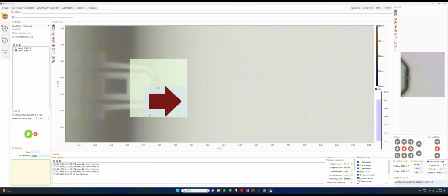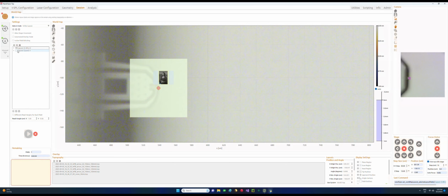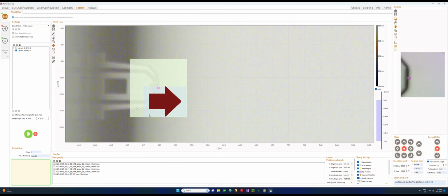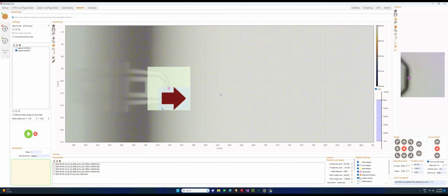We will see that this arrow is relatively big for a Nanofrazor geometry. Like the Mona Lisa, for example, is quite smaller, and patterning with TSPL requires 3 minutes and 30 seconds. The arrow is definitely bigger, and it only takes 20 seconds. So this already shows why the laser is such a nice feature in the Nanofrazor Explore, because it allows us to have a much faster patterning for areas that do not require a very high resolution, like this arrow, for example, or if you want to make contact paths or contact lines.